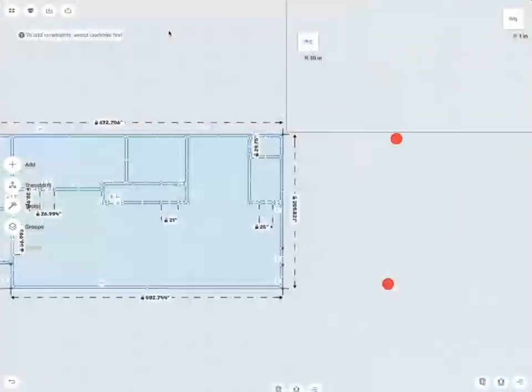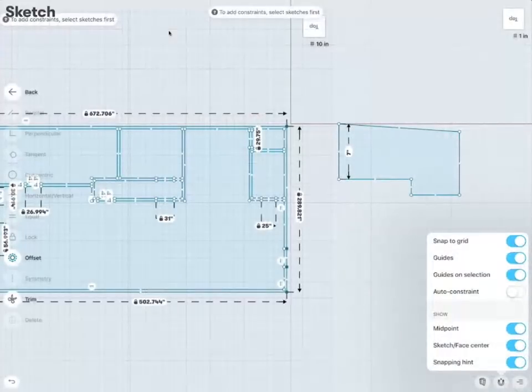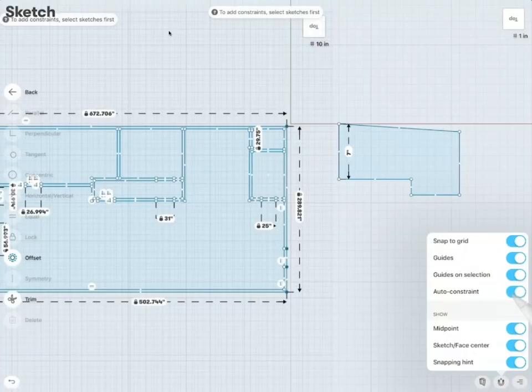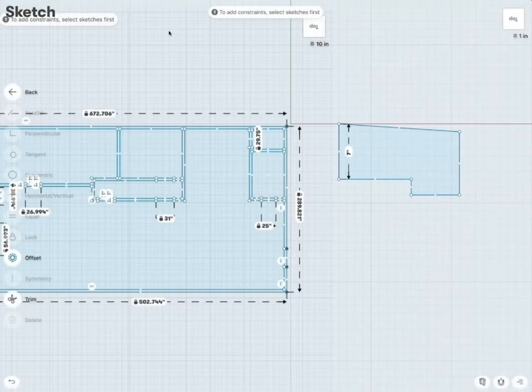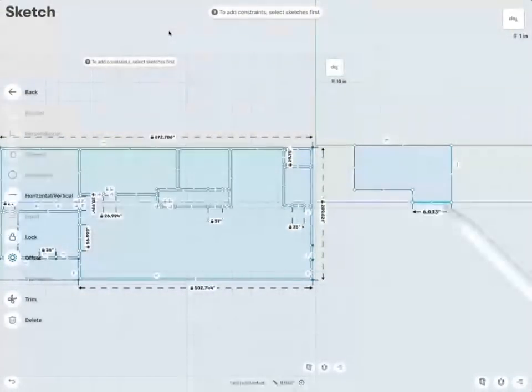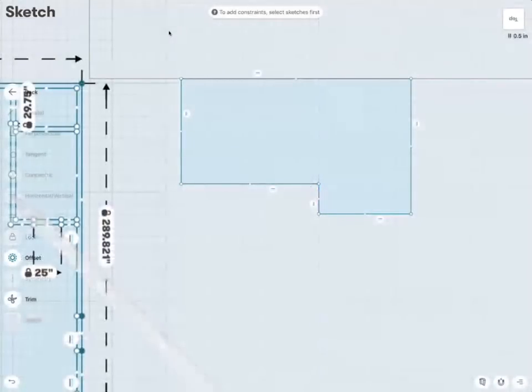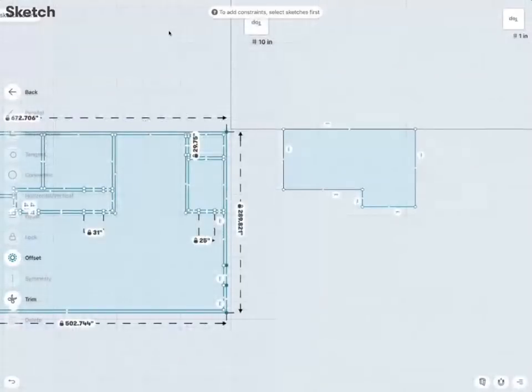In Shaper, we can actually just start sketching. So on the right side, I will just do a very primitive, basic sketch. And as you might have noticed, for those who are familiar with Shaper, no constraints were added right now. I have auto constraint turned off. So the first thing I will do after I create the lines is select each line and then add the correct horizontal and vertical constraint. I prefer working with vertical and horizontal instead of perpendicular. This way, I always know exactly how a line should be.